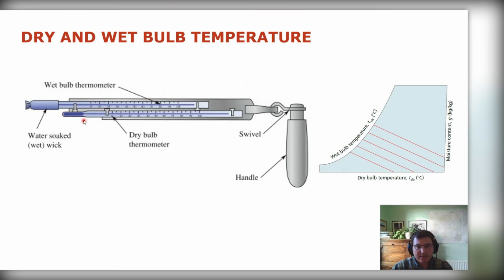Well, the dry bulb just measures the temperature of the air. The fact that you're moving through the air makes no difference. But the one where water is evaporating because of the movement, we get a cooling effect. Remember what we said, when you evaporate some liquid, that absorbs a lot of energy. So therefore, it will have a cooling effect on the bulb that's measuring the temperature. The more evaporation we get, the higher the cooling effect. So what it means is that if this is very dry air that very easily evaporates, there's very little moisture in the air.